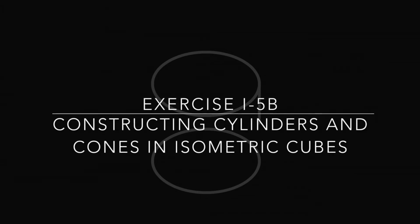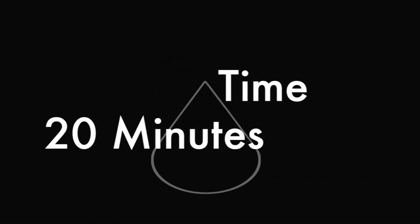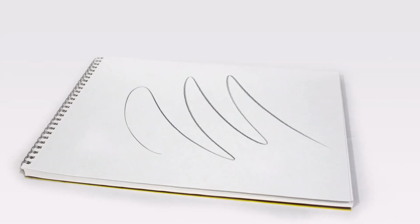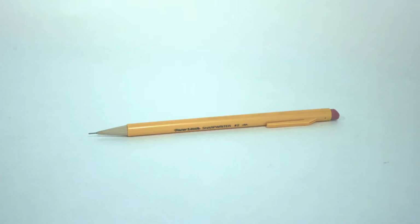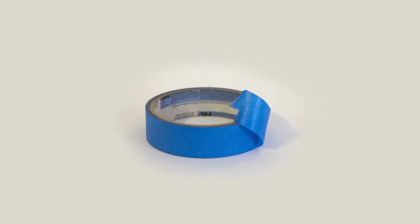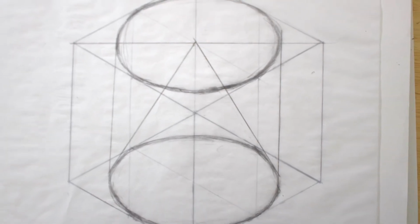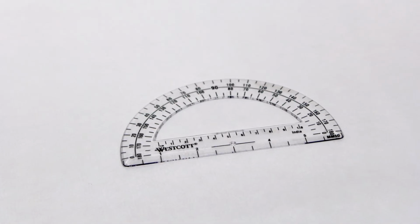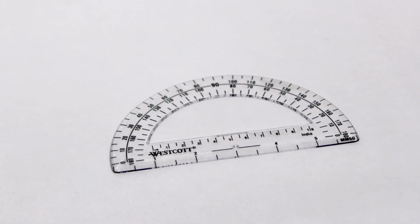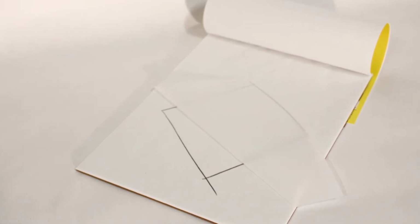Exercise I-5B, constructing cylinders and cones in isometric cubes. Time, 20 minutes. Materials, sketch pad, tracing paper, mechanical or number 2 writing pencil, protractor, eraser, tape or clips. Subject, cylinders and cones in cubes. In these exercises, we'll use the protractor to make it easier to draw basic forms and use tracing paper to draw one image over another.